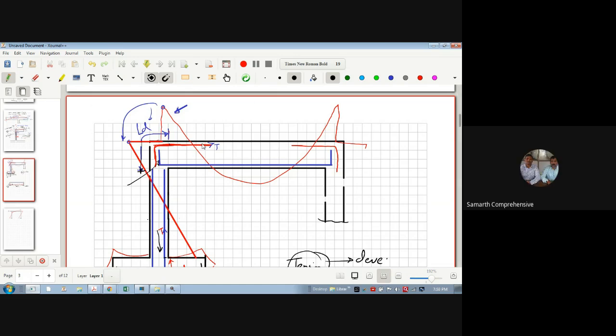See, flexure tension failure means, let's say this is your 100 kilonewton moment. This bending moment is 100 kilonewton. That means you need to design this bar for 100 kilonewton moment. How will you design that? So Ast is equal to, I'll just take the simple formula, Mu upon sigma st into j into d. You know how to calculate the steel.